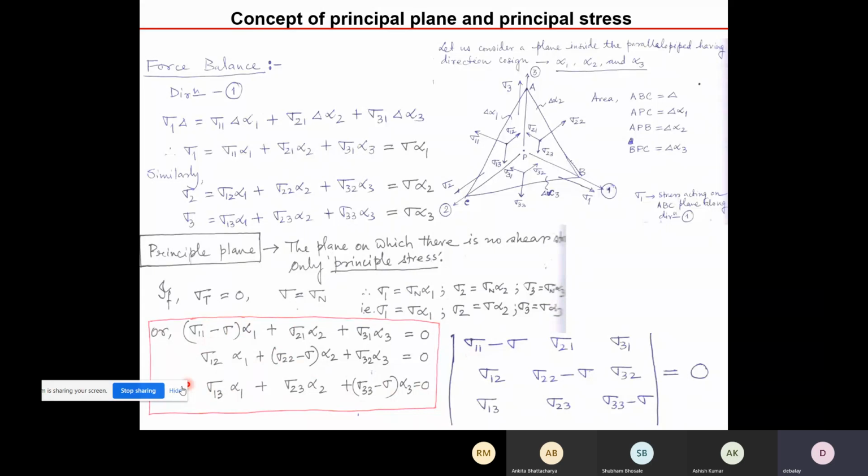How much stress is acting along direction 1 in a body can be written as sigma 1 1 equal to 300 MPa, sigma 2 1 equal to sigma 1 2 equal to 140 MPa, sigma 3 1 equal to sigma 1 3 equal to 40 MPa, sigma 2 2 equal to minus 100 MPa, that is compression of minus 100, sigma 3 3 equal to 0, there is no stress, suppose. So basically the stress tensor components are real stress values.